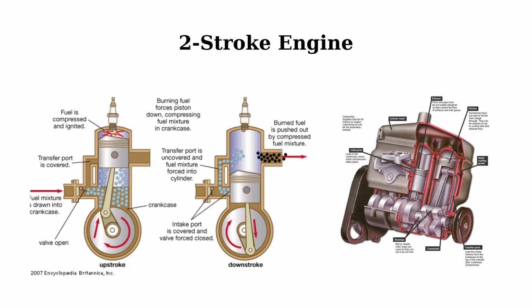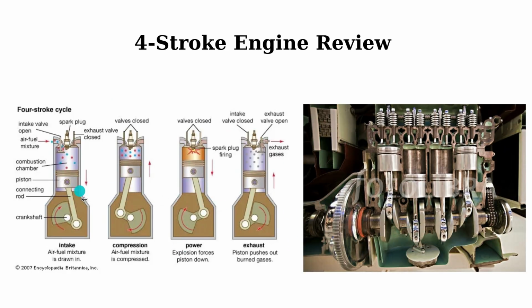They are less fuel efficient. This is because some of the fuel can escape during the process because it doesn't use valves. The fuel can escape during the process. They also produce more pollution because combustion isn't as controlled as in four-stroke engines.